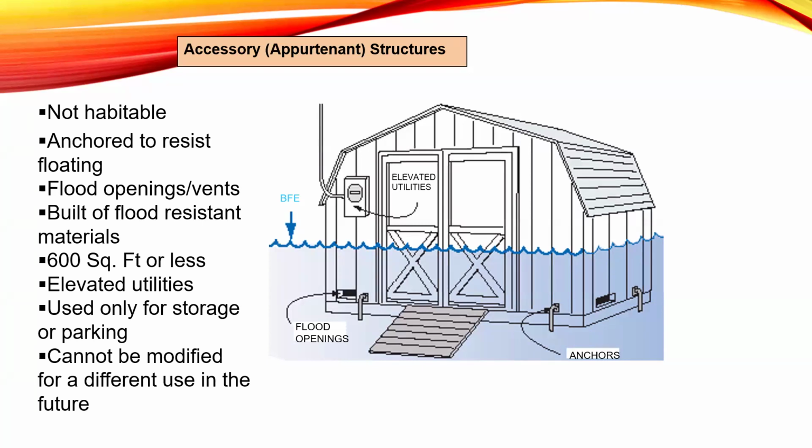So these are probably the most common violations that we see when we do our audits. People will just pick these up from the store. Many of them are just pre-made and you just have them delivered and installed. And many of them are not compliant for floodplain use, so they don't have the vents or are not meeting the other criteria to be allowed to be wet floodproofed.